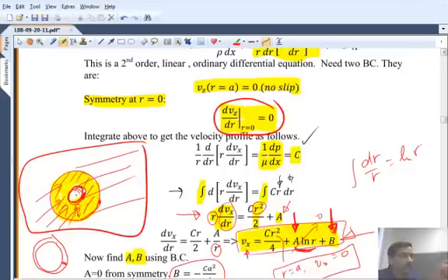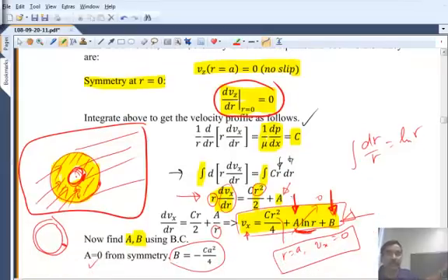So to answer your question, that equation does not apply when you go into turbulent flow. But it does apply for classes of laminar flows where the geometry would be variations on these. So it does apply for both pipe flow, which is completely filled with fluid, and concentric annulus as well.